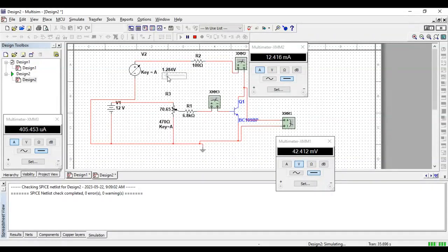So this is 100, it is 35, around 39, then 0.2, it will be around 70. Now the transistor is in the active region. Again, change the value to 0.3, it is 82. Again, change it to 1 volt, it is 83. So now the transistor is working in the active region.